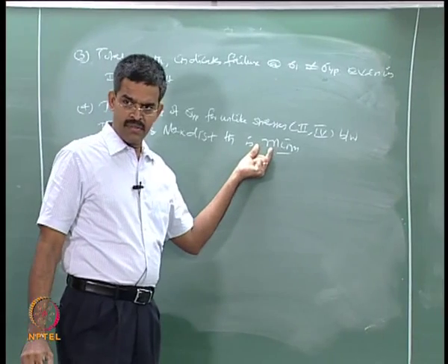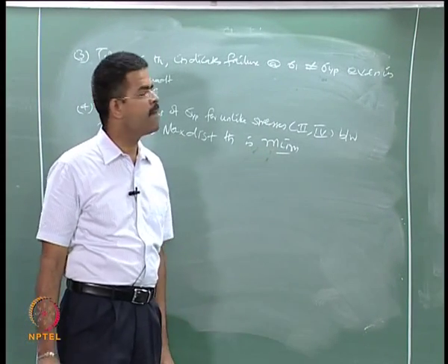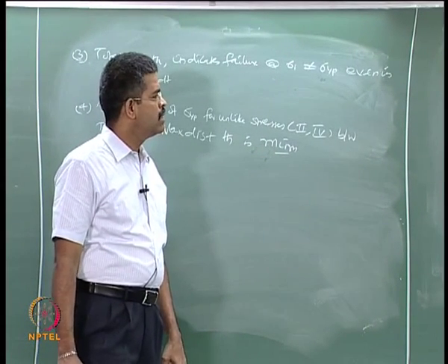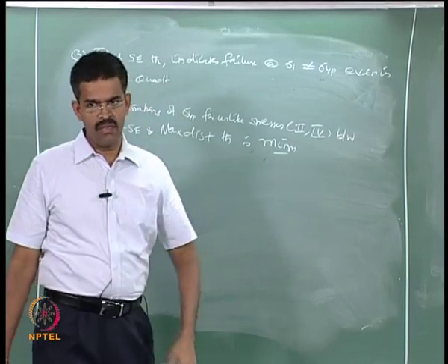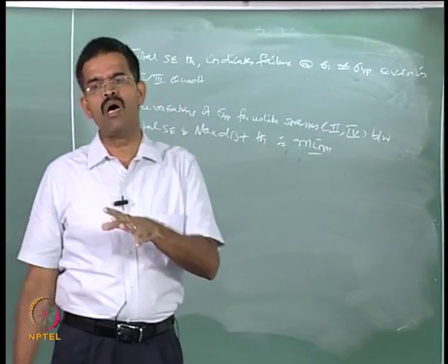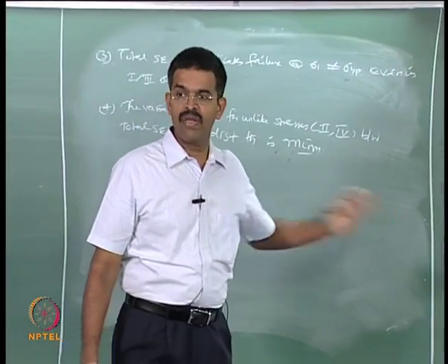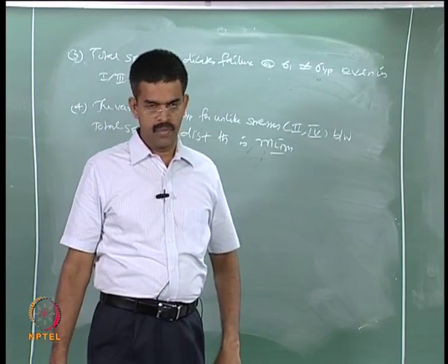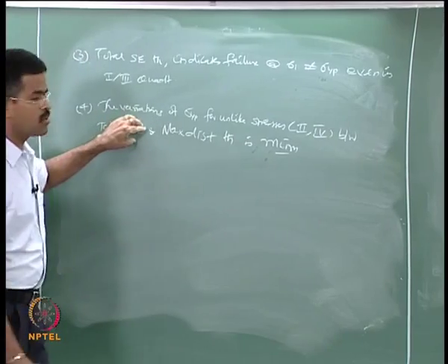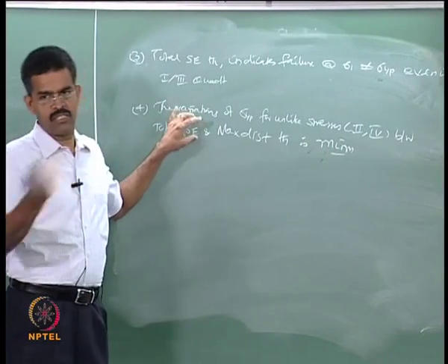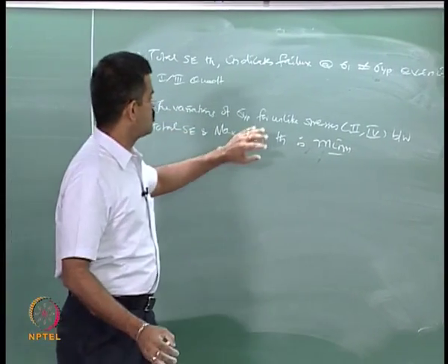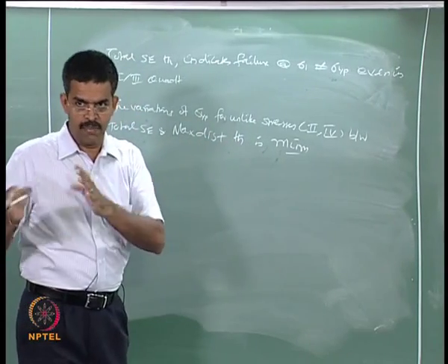This information can be interpreted as: change of shape in the body will not cause serious deviation in failure. Maximum strain energy includes volumetric as well as distortion. Maximum distortion talks only about change of shape.